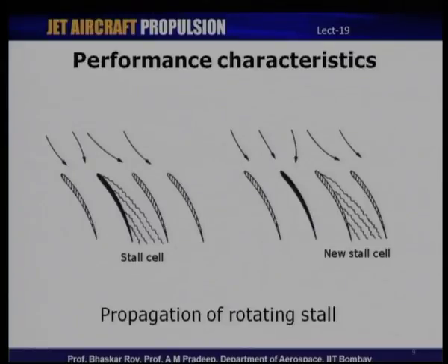The difference between what we see here and a centrifugal compressor is that what I have shown here is basically a set of aerofoil blades, which is not really the case in a centrifugal compressor. We normally do not have airfoil blades for the impeller. Impeller blades are basically vanes and not necessarily airfoil sections, but the phenomenon is the same and affects a centrifugal compressor as well.